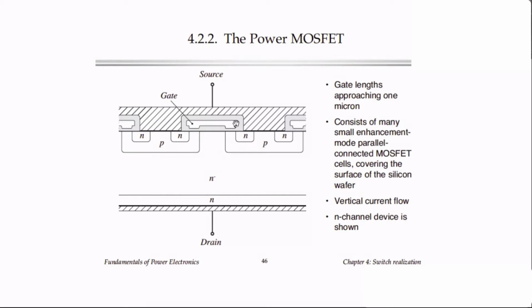And then we have the doped silicon. This is an N-channel MOSFET. The source is connected right here. The drain comes from the bottom at this N region where there's slightly doped material, and the drain is actually right there. So we have a MOSFET that connects to the drain and source like that. The P material is called the substrate, and in a practical power MOSFET, that substrate is shorted to the source.